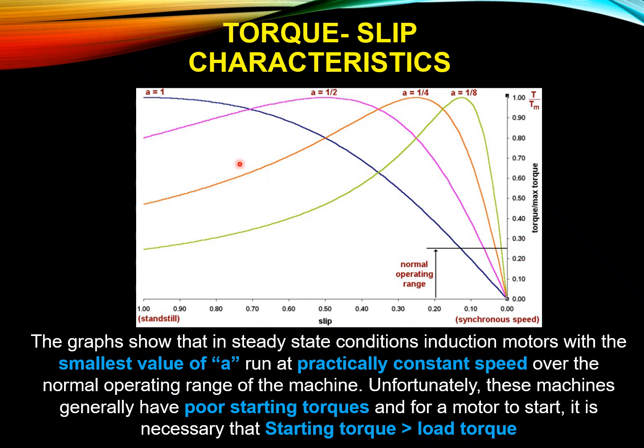So here you can see it's poor, not like a equals 1 with maximum starting torque. For a motor to start, it's necessary that the starting torque is more than the load torque.